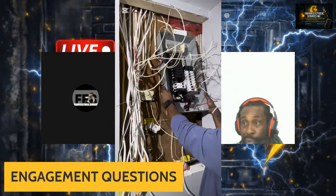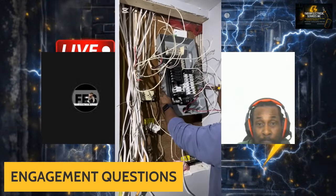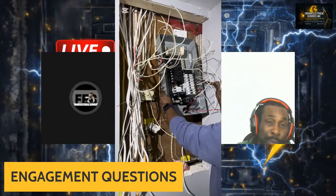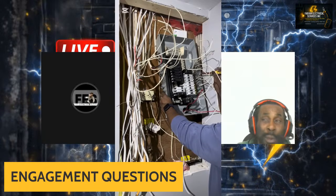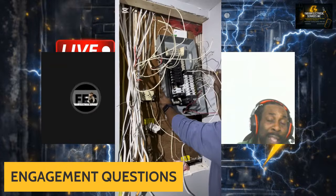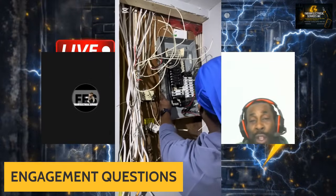I have limited space to work with, so you don't just swap out your panel and forget about labeling the wires before you actually take the panel off. You remove your wires from the breakers and label your wires before you remove them from the panel. Once everything's labeled, then you can remove your cable from the panel and you're good to go. It's going to save you a lot of time at the end of the job.